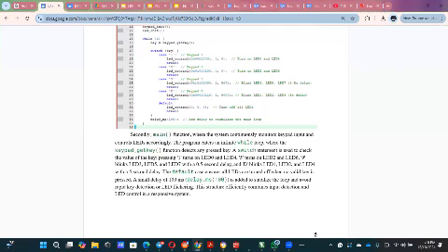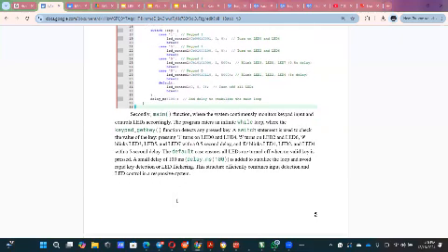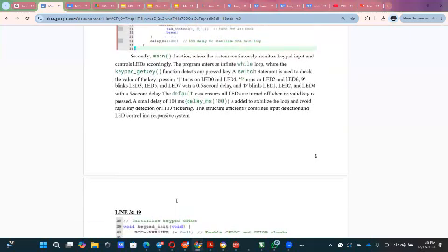The default is to ensure all LEDs turn off when no valid key is pressed. A small delay like 100 milliseconds is added to stabilize the loop and avoid rapid key detection or LED flickering, which ensures the structure efficiently combines input detection and LED control in a responsive system.